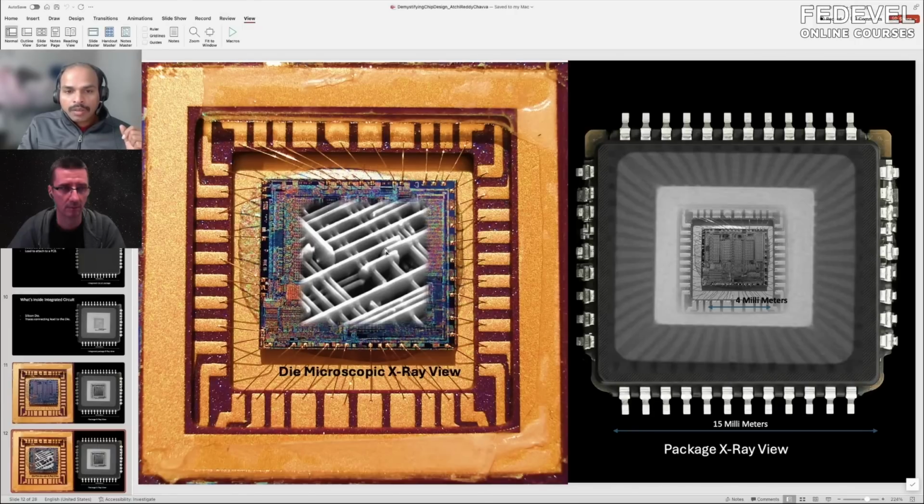You see this little notch here where I'm pointing? Even that could have a significant influence on performance, because of what we call crosstalk. The signal running in one electrical wire can influence, just like an electromagnetic effect, the neighboring wires or structures, and generate noise. Now the device, the transistor, needs to be robust enough to isolate or identify these situations.